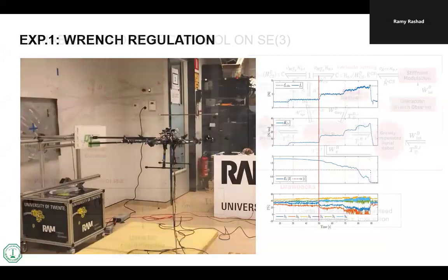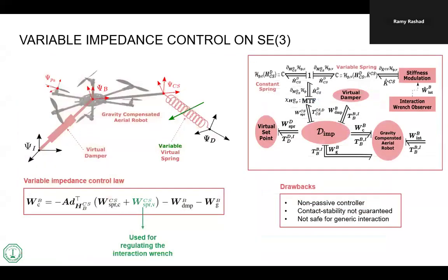If you go back to the bond graph, you can rewrite it as a spring that has variable k, so the k is now time varying, so it becomes actually a state, not just a constant. So I need to provide k dot. Where does the k dot come from? It comes from some sort of signal processing algorithm that does some PI controller on the force or on the wrench.